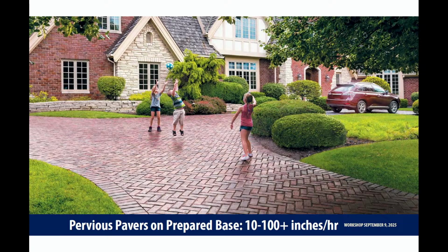A lot of those have a little tab stub, a piece that bumps it out, so it's not like a traditional brick paver that's an absolute pure rectangle. It's got essentially a built-in spacer, so it's pretty idiot-proof for that matter. It can only go together so tight, and then that void is what creates the pervious part of it, provided they put the right base below it and then the right infill sand grouting.